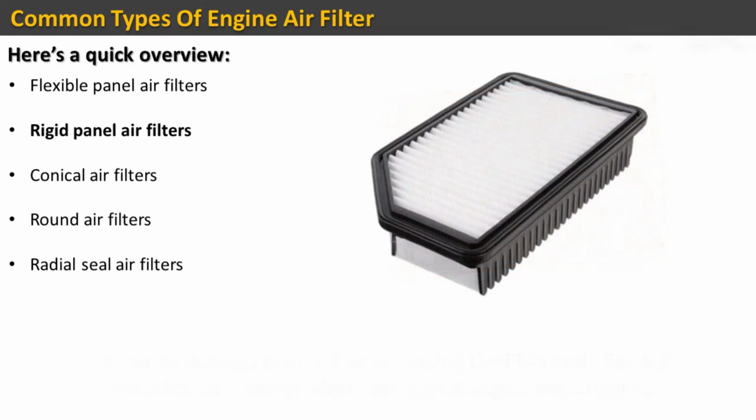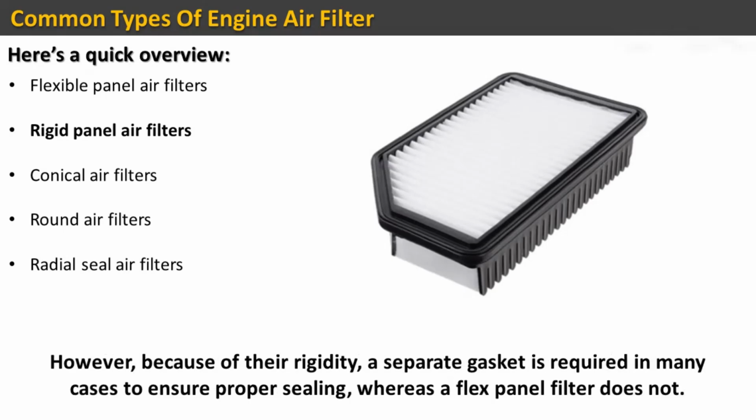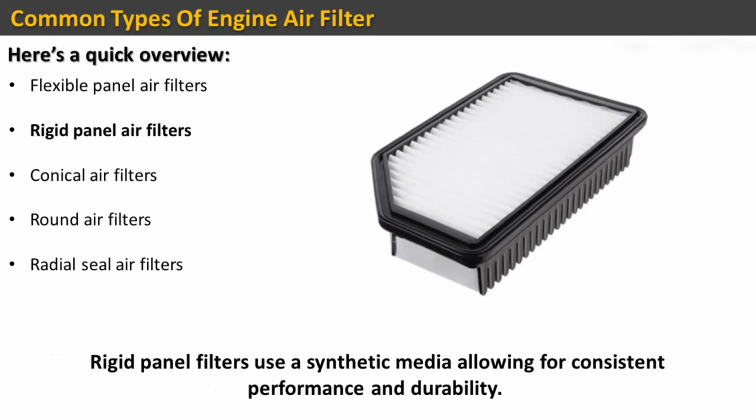Rigid panel air filters. With a solid frame made of rigid plastic, these filters maintain consistent shape and performance. However, because of their rigidity, a separate gasket is required in many cases to ensure proper sealing, whereas a flex panel filter does not. Rigid panel filters use a synthetic media allowing for consistent performance and durability.